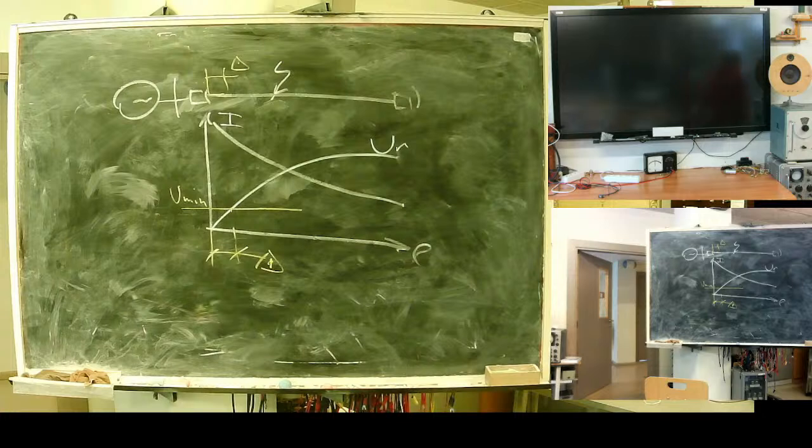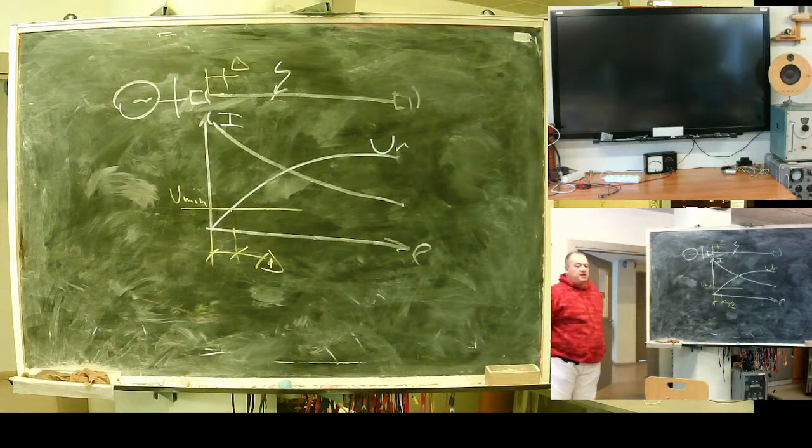It is highly probable, because of miscommunication between contractor and dispatch, lineman still working, dispatch gets command to switch line on. And you get fault at 0 kilometer, at 0 distance. In such case, switch on fault, there will be nothing in relay memory and memory function becomes useless.